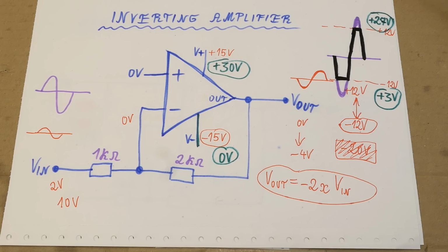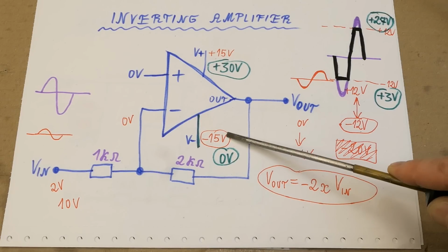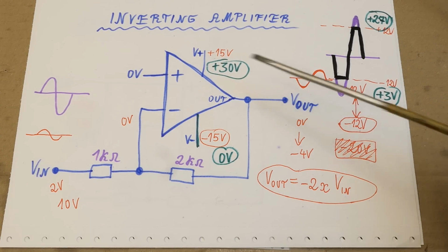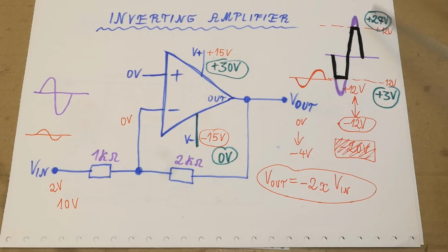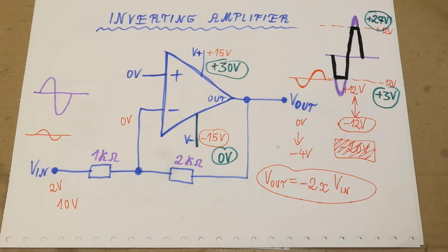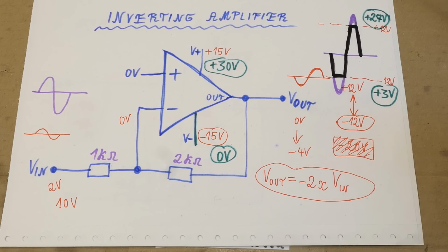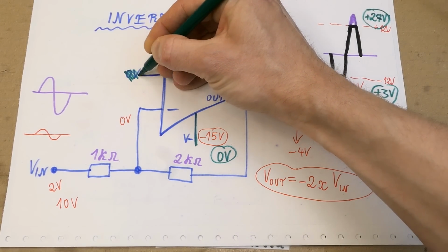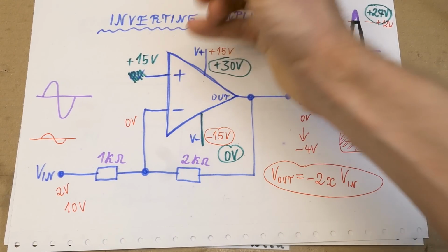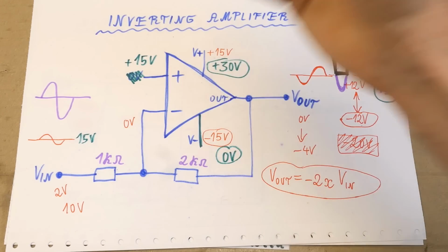And if the datasheet says plus and minus 12 volts output voltage swing with a plus and minus 15 volt supply rail, then of course with a non-symmetrical 30 volt power supply, it will be from plus 3 to plus 27 volts. Everything in this example is just shifted 15 volts up. And to operate this example circuit with a non-symmetrical supply voltage, it will of course not work with 0 volts here. You'd have to, let's say, center it around 15 volts. And also the input voltage would have to be centered around 15 volts, let's say.